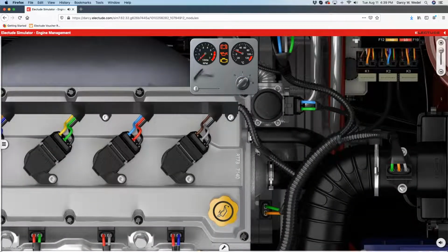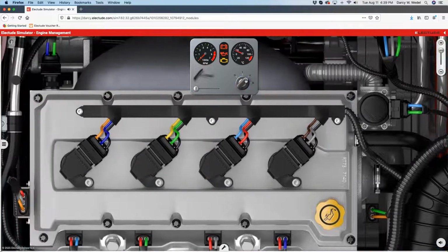While they're cranking this thing here, you can hear the engine running. If you zoom in, it's almost like getting a stethoscope out, and you can see that the engine's there. It actually started and ran a little bit, but when I accelerate, it just falls out and stalls. We can see that it has RPM, that the check engine light comes on, and you can hear the main relay clicking on and off. So there's information you can glean just through listening.